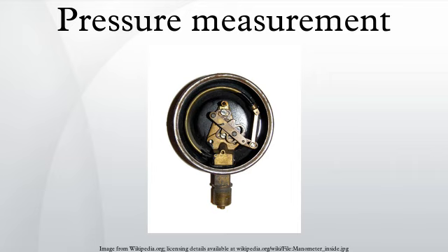Atmospheric pressure is typically about 100 kilopascals at sea level, but is variable with altitude and weather. If the absolute pressure of a fluid stays constant, the gauge pressure of the same fluid will vary as atmospheric pressure changes. For example, when a car drives up a mountain, the tire pressure goes up because atmospheric pressure goes down. The absolute pressure in the tire is essentially unchanged. Using atmospheric pressure as reference is usually signified by a g for gauge after the pressure unit, for example 70 psig, which means that the pressure measured is the total pressure minus atmospheric pressure.